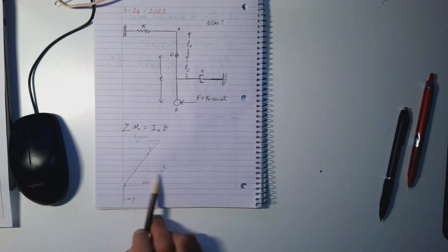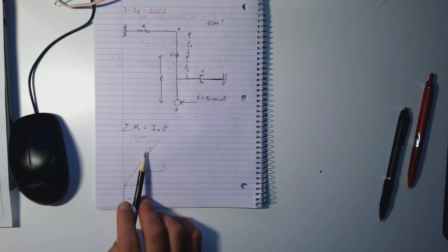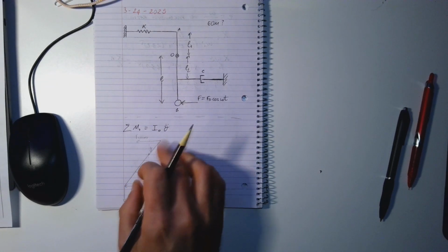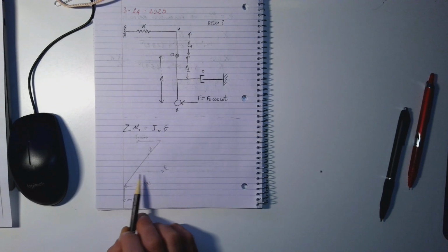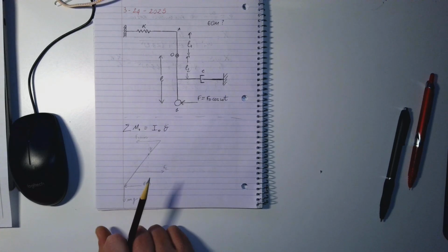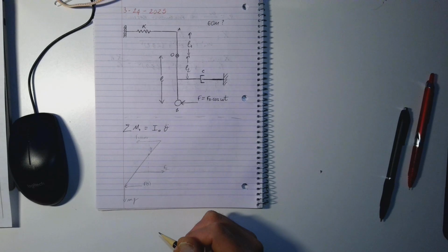We also know that this force from the dashpot acts in this direction, because if we have that theta is in this direction, it means the rod is rotating clockwise. It means that this force, which depends on the velocity of the bar, is trying to slow down the rotation of the rod, which means it is opposite with respect to the rotation itself. Make sense? Any question about this?